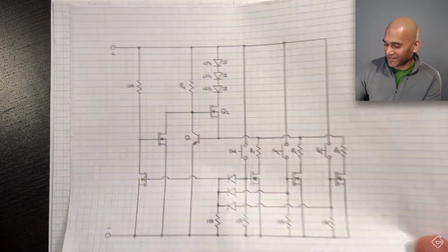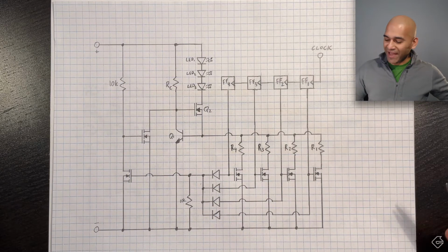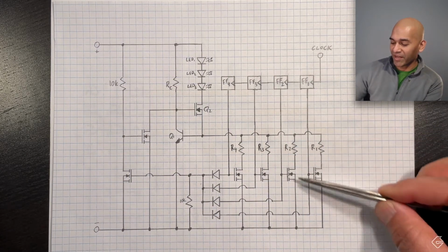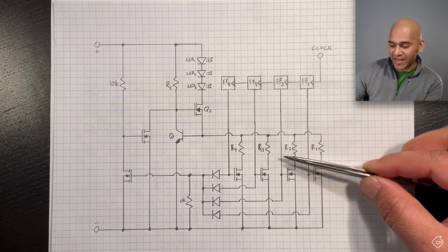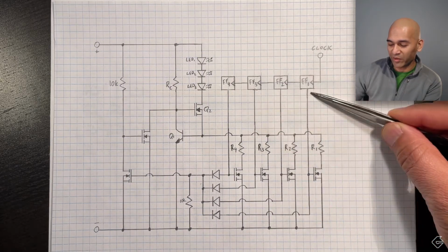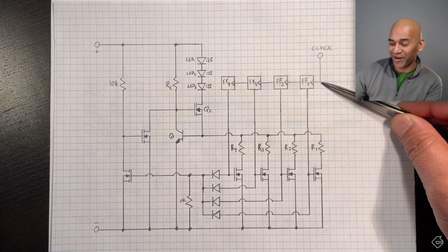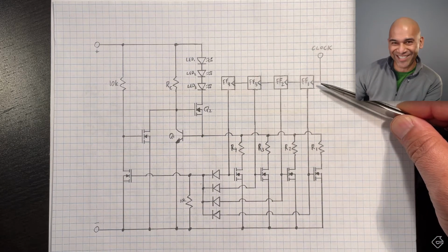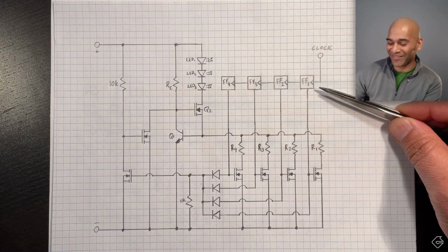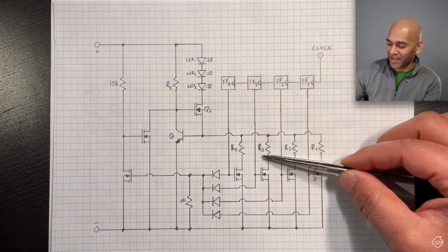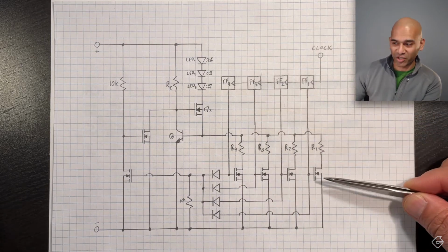Here's the updated circuit down here. So I've added a 4th current path. There it is. You can see it right over here. The switches are now gone, and in their place, I have an output from all these 4 flip-flops. And the flip-flops are being fed by our new clock pulse that we just generated using the 4007 chip. So this has been generated, and it's going to trickle down through all of the flip-flops and cause these MOSFETs to turn on and off.